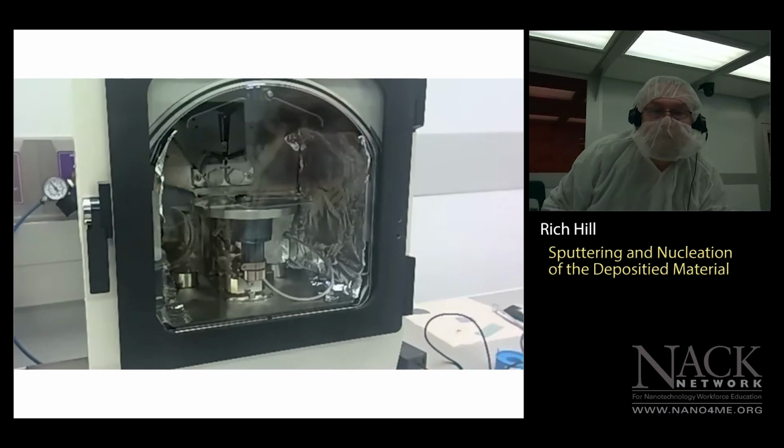And all I have to do here is we have a screen, and it's all software driven, this Leica. So this sputter coater is all software driven. I have a gold target in there. I have it set to put approximately 3 nanometers down of gold. And all I've got to do is press start because it's under vacuum already. And the process should start going. Let's hope it registers. Yes, it's doing its purge cycle now.